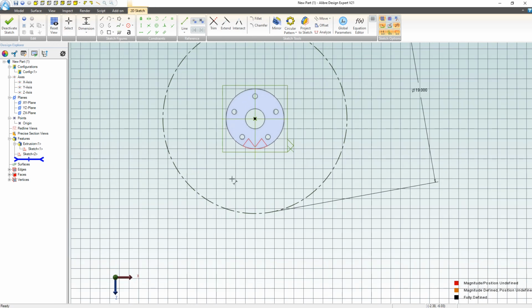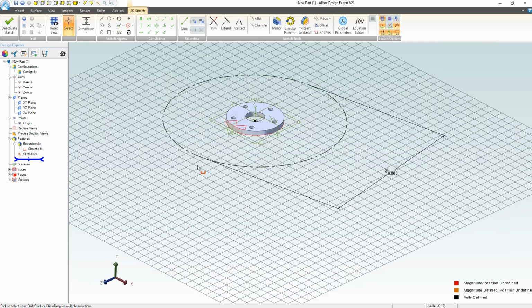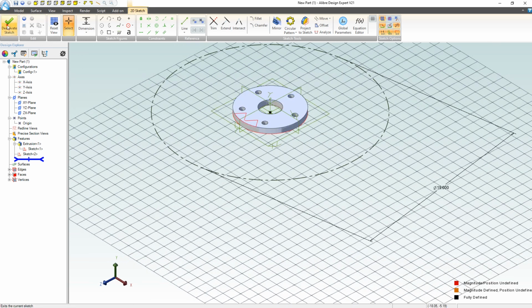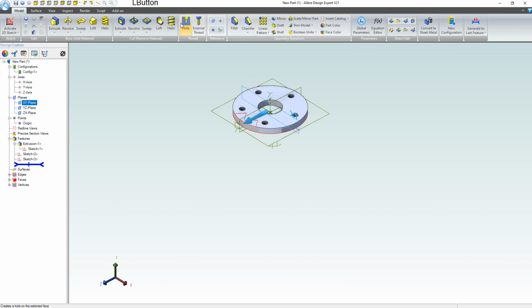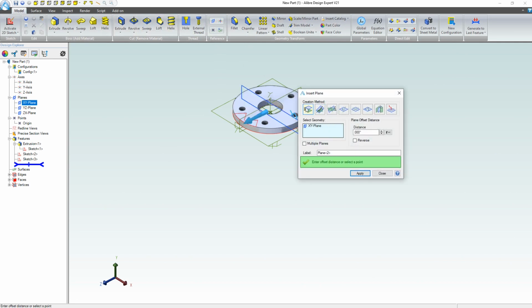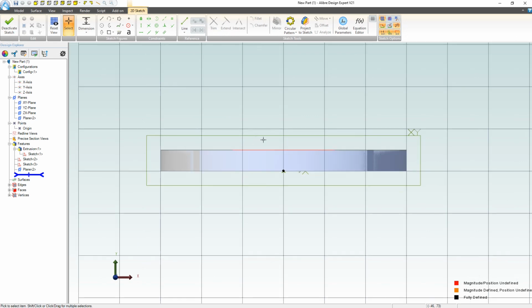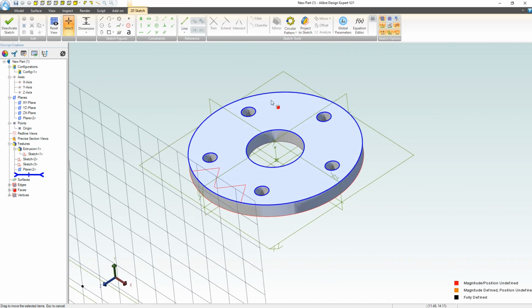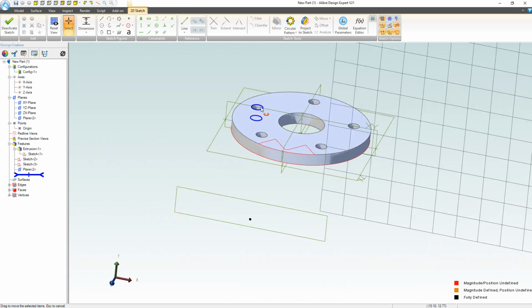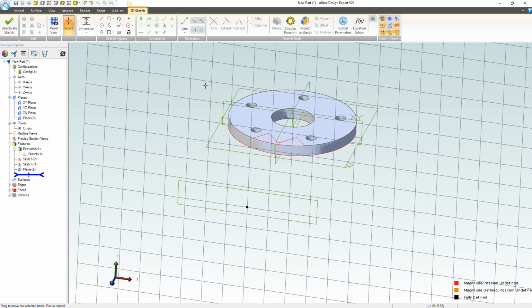19 inches in diameter. Now I want to define a plane so that I can loft my spoke a little bit past what we're doing here. So let's make a plane. Where's reference geometry? There it is. There we go. We're going to say distance 9 inches. We're going to apply and close. Now I can sketch on this plane. This is also where we would define the offset of our mounting plate. So let's activate a 2D sketch here. And yes, this is looking good, right? So we have our 2D sketch. Let's get our view normal again. How do I do that?